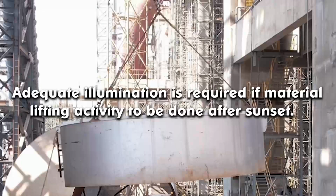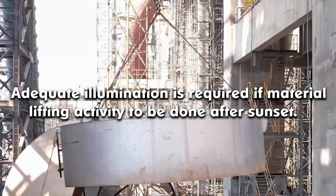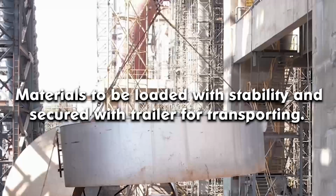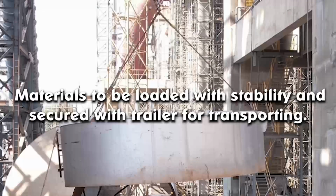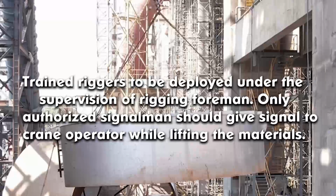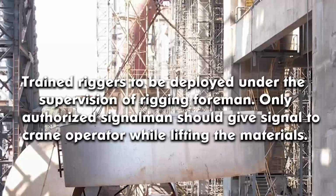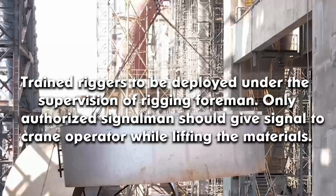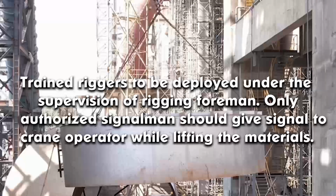Adequate illumination is required if material lifting activity is to be done after sunset. Materials to be loaded with stability and secured with trailer for transporting. Trained riggers to be deployed under the supervision of rigging foreman. Only authorized signalmen should give signal to crane operator while lifting the materials.